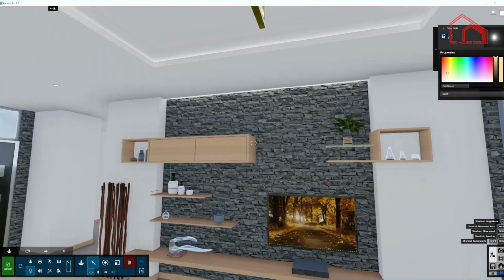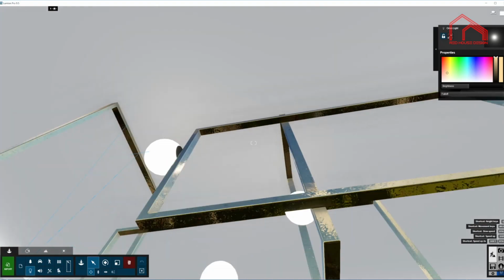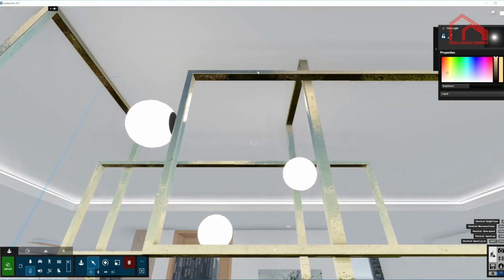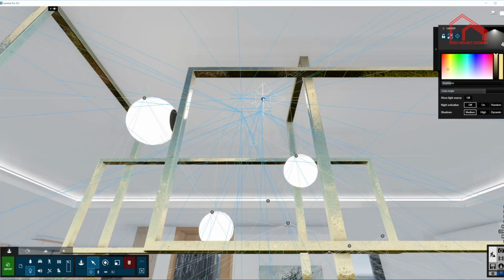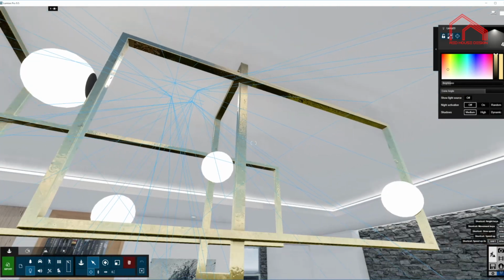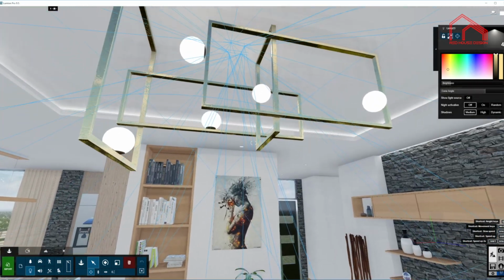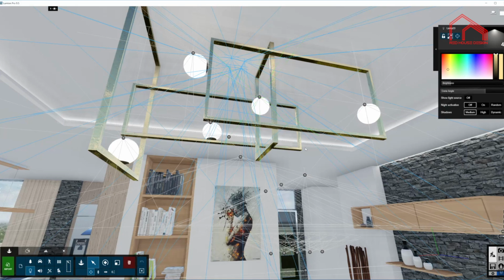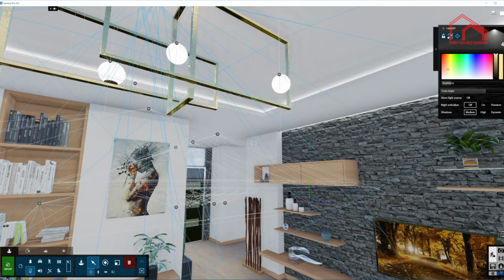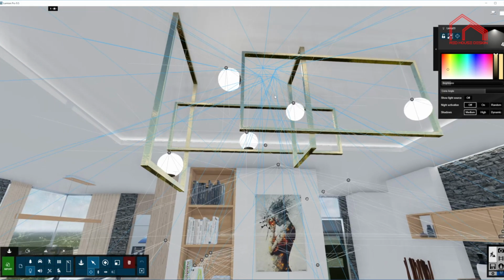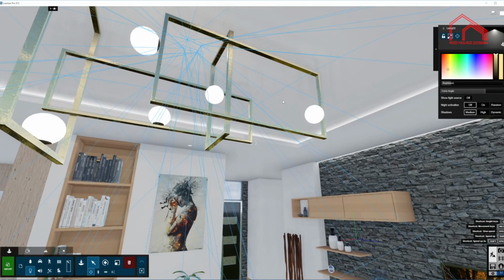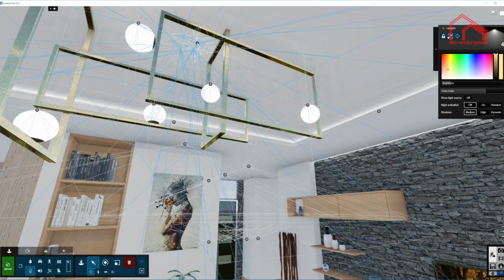And now moving on to these spotlights, why I actually put them in here. Here they are, as you can see, 4 of them. The reason being, I'm complementing the light from these Omni lights. As I mentioned, Omni lights would not cast shadows, and obviously when light is emitted in real life and has got an object in its path, it will cast shadows. So that's the reason for these spotlights. I'm using 4 of them, 1 for each side of the room.